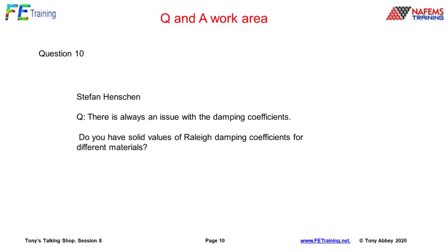Stefan says there's always an issue with damping coefficients. Do you have solid values of Rayleigh damping coefficients for different materials? I don't actually like Rayleigh damping because we are defining a basic quadratic variation of damping as a function of frequency.